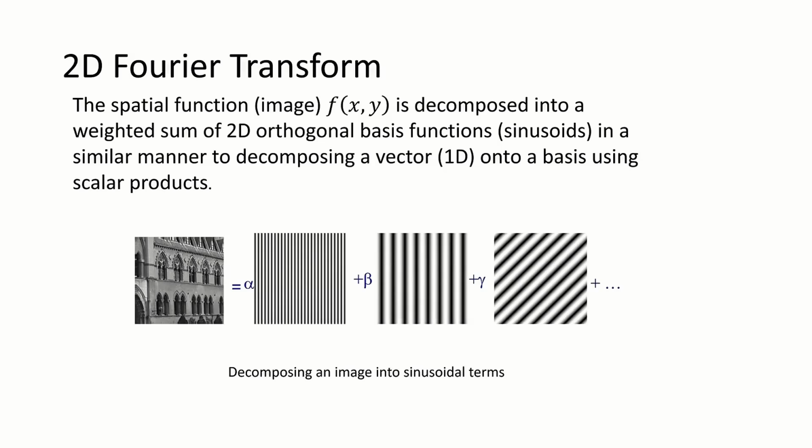If this definition is valid for both the Fourier transform and the wavelet transform, the only difference is the basis function. Here we are using sinusoids, sine and cosine. In wavelets we use wavelets. We decompose the signal into wavelets. What is a wavelet? A wavelet also has some frequency, but what is a sine? A sine goes on and on, and you can make it a cosine. But a wavelet is a small pulse that is present only for a short duration. It has more prominent edges and dies down quickly, a very short pulse.